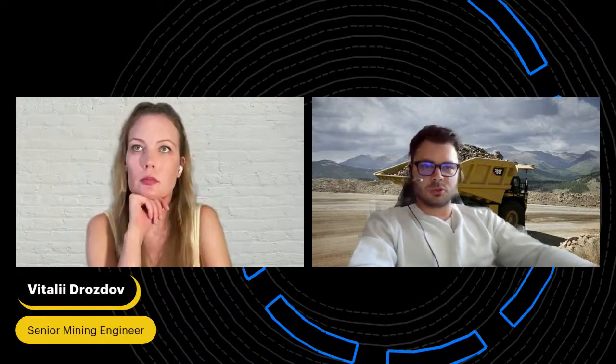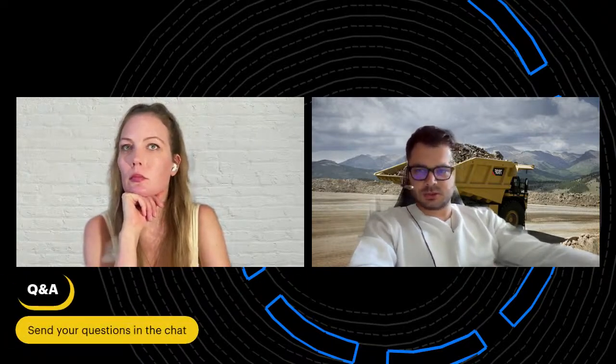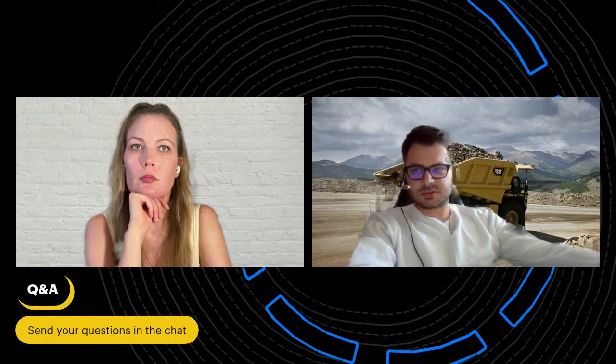Okay. Actually, our presentation is about key themes, because all of them can't be covered. We just would like to highlight the main ones. But as a mining engineer, I would like to say that in the beginning of a mining project, you should take into consideration all of the possible aspects of this specific mine. For example, if there is a lot of water, you should think about trenches and about watering, as we talked about. Then you should avoid switchbacks if it's possible, of course.